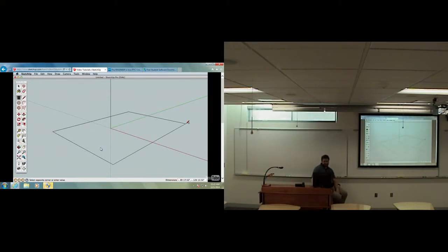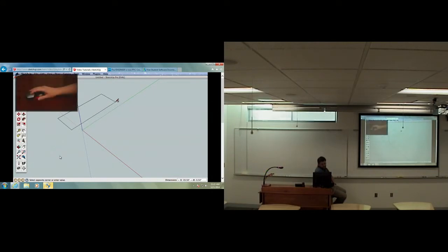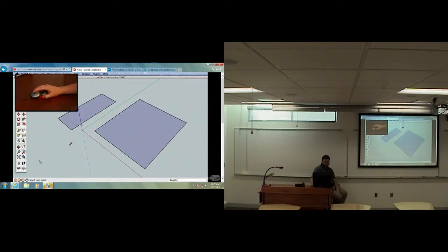Again to finish, a quick note about drawing in SketchUp. Get in the habit of click and releasing your mouse button to start and finish most actions. You don't have to hold it down. This will hold true for almost all of the drawing tools. So there's one difference between using a mouse in, like, Word, for example. If you want to create a rectangle in Word or in PowerPoint, you go up to your drawing tools, you hit the rectangle tool, and you drag. You click and drag to create your rectangle. In SketchUp, you don't. You click to start making the rectangle, and then you make the rectangle as big as you want, and you click to finish making your rectangle.